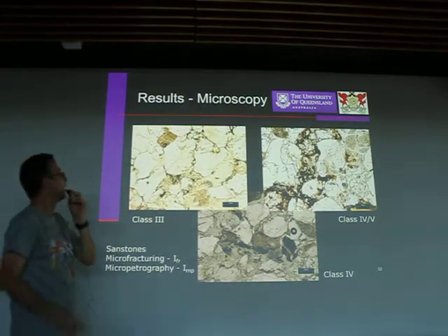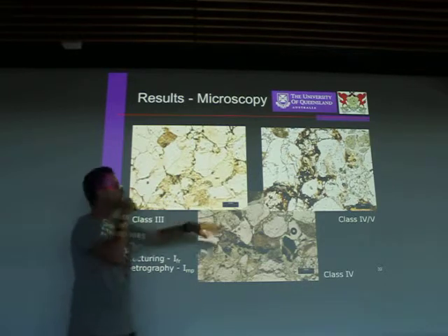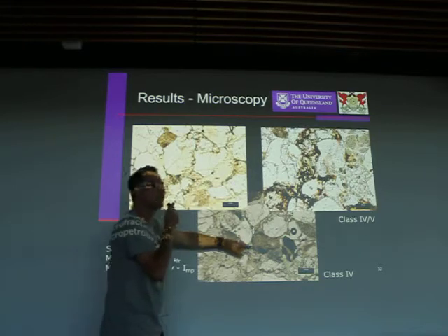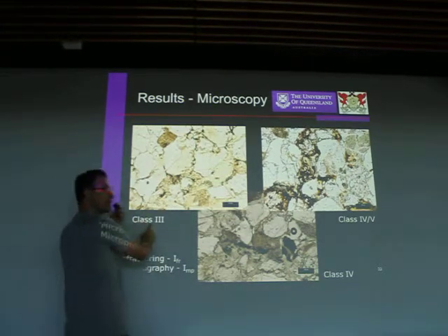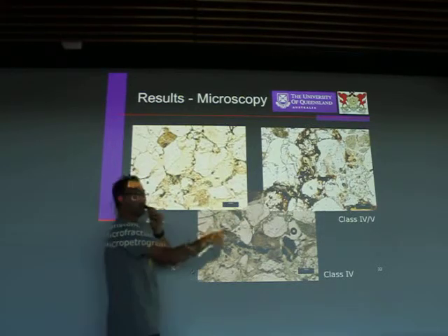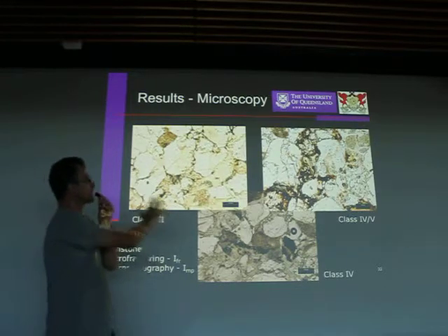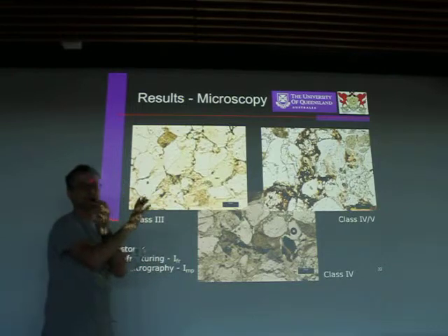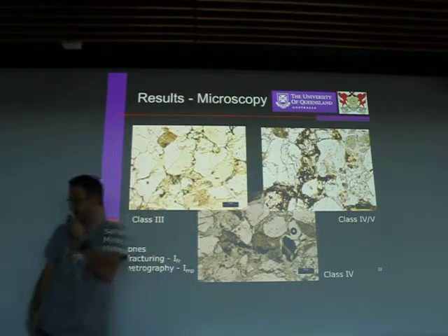So here the same for sandstone. You can see that the iron oxide content is lower, but there is an increase in the iron oxide content from more sound materials to more weathered materials. Also, there is some clay mineral production here. It cannot be seen in this uncrossed nicols image, but you can see it when you take a look at the crossed nicols image as well that I have made.